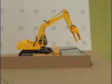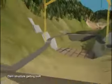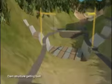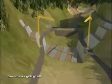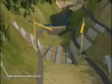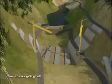Concrete is placed in layers of about 300 mm thickness along the block width in a 3-meter layer at a time so that cold joints during placement are avoided. With slabs spanning the width of the dam, the entire structure is eventually built.